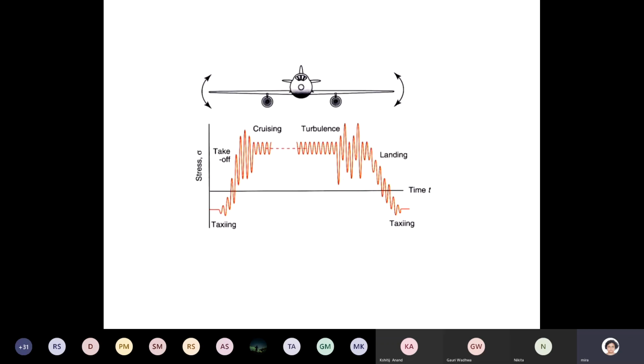There are two alloys of aluminium, Al2024 and Al5056. Al5056 has a much lower yield strength than Al2024, but it is preferred in certain portions of the wing because it has much higher fatigue resistance as compared to Al2024.